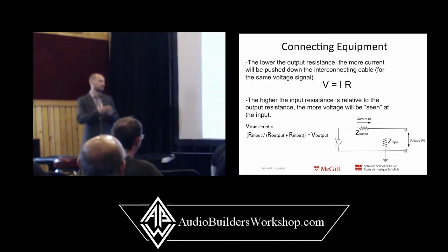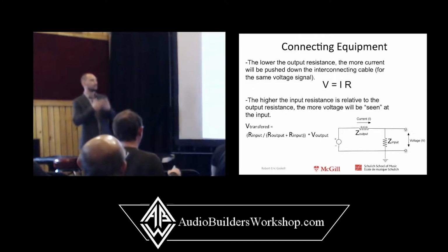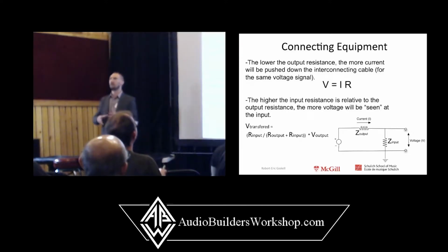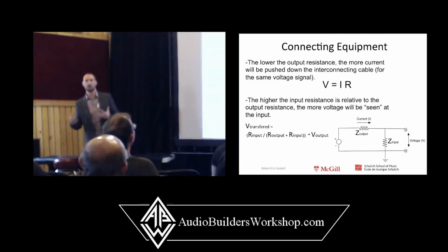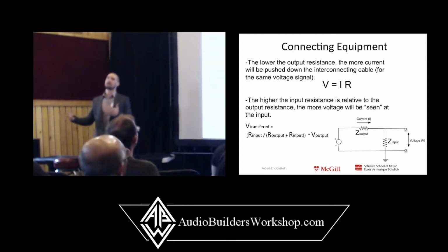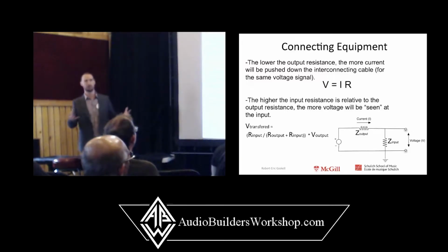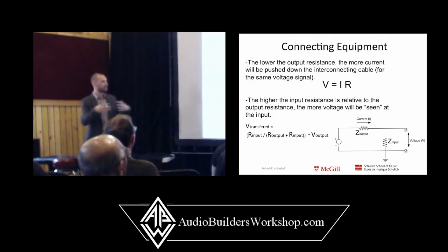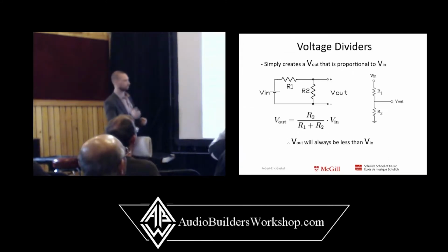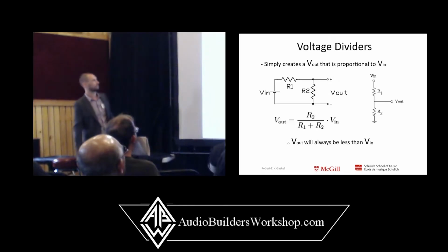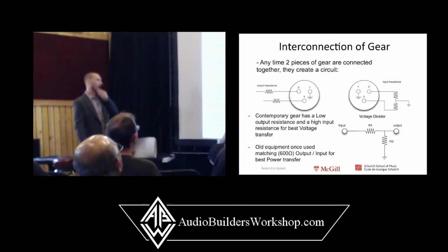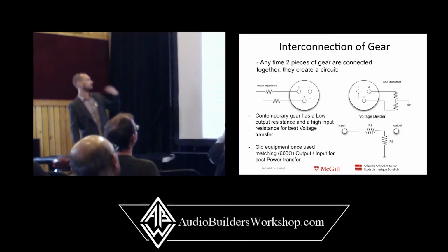And if the output impedance or input impedance have reactance, if they have some capacitance, if they have some inductance, like if there's a transformer, then there's a potential that that voltage divider will create a different amount of voltage transfer at different frequencies, which will change the frequency response of the signal that gets transferred from the microphone into the microphone preamplifier. So we're creating this circuit by plugging the mic into the mic pre.